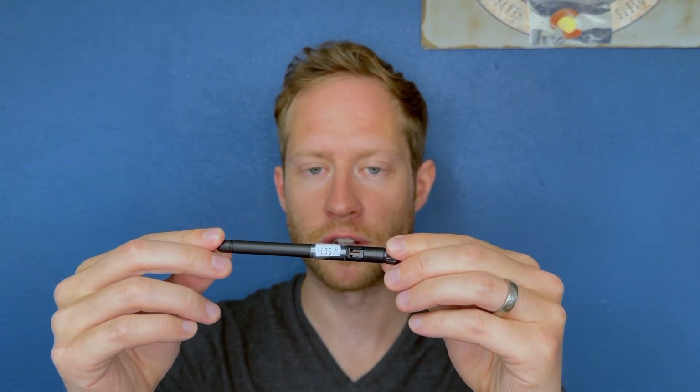I will be doing a screen share alongside of the blog post. Taking a step back, we do have the SDR. This is an SMA type connector. Along with that, I got 3 different antennas. Number 1 is a 433 megahertz antenna. This one is for the temperature sensors and stuff like that around your neighborhood. This one is 978 megahertz, which is an ADS-B frequency. This one, I don't know where any of my 915 ISM antennas are, but this one's close enough. And this is 1090 megahertz, which will be for the main aircraft ADS-B signals.